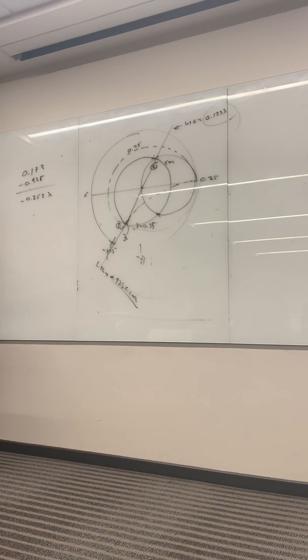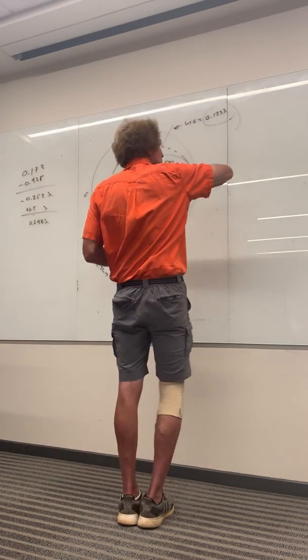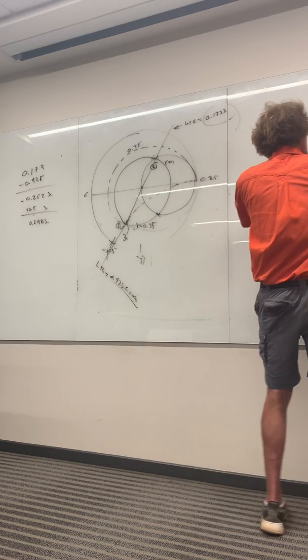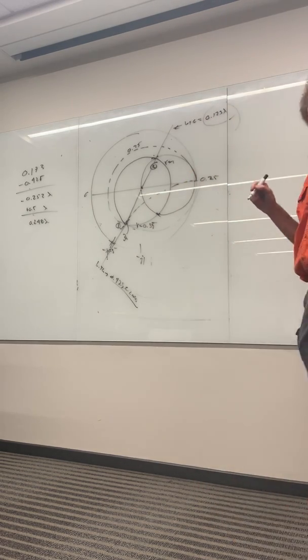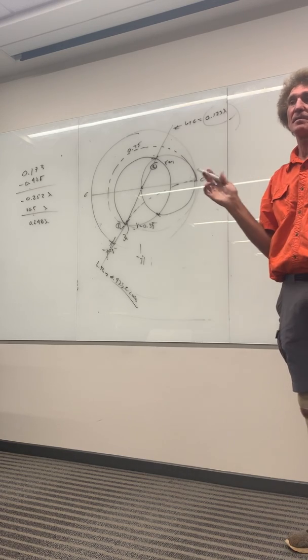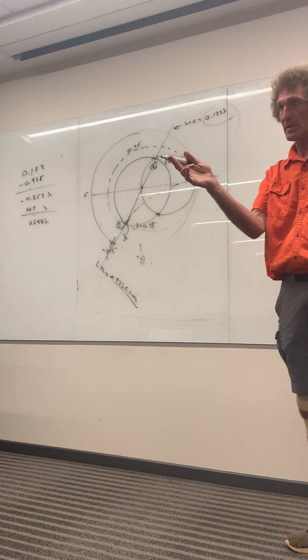Add a half wavelength. That's right, we just add 0.5. So we add 0.5 lambda to this, and what do you get? 0.248 lambda, right? So that's this length here. You have to move from this point to this point, which is just about a half wavelength. So this D is 0.248 lambda. If it was 0.25, or an exact quarter wave, that would be a right answer too. He probably wanted a quarter wave. Are you with me? You follow me on this, Duncan?